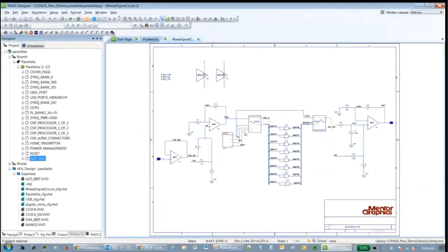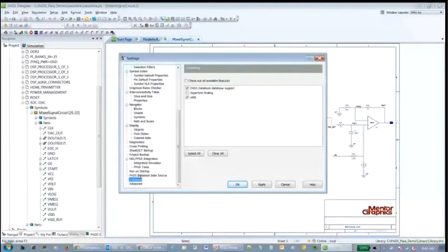So I'm just going to click on this part. This happens to have it, but if I did have an IC in here that had VHDL code under it, I can click on that and tell it to launch ModelSim in this case. But if I go to my setup here, I can also tell the tool to launch any integrated tools that I might be using, like the Xilinx tools. If I'm using Altera for a simulation engine for some reason, I can tie those applications into here via settings. And again, when I right click over something, I could launch my FPGA tool right from my schematic.